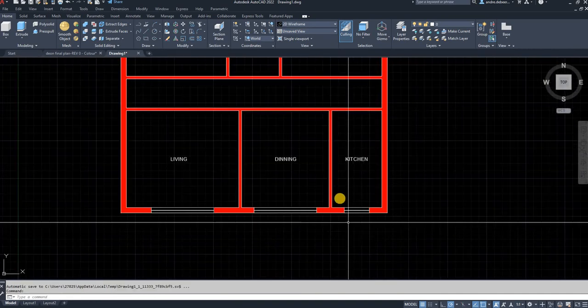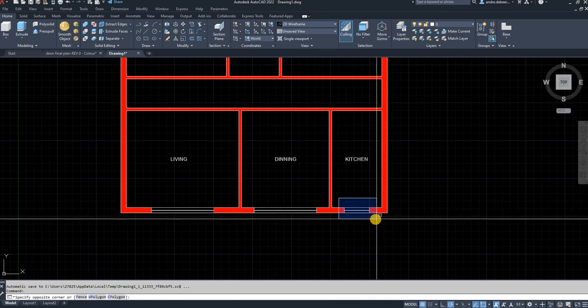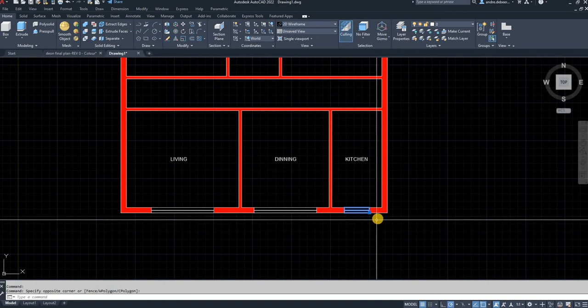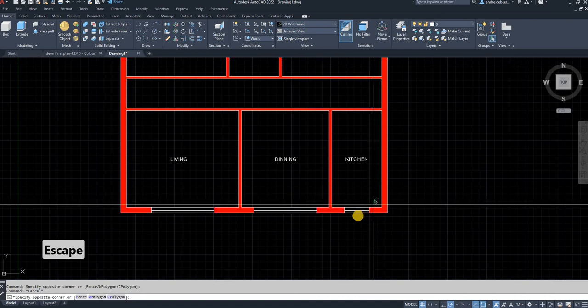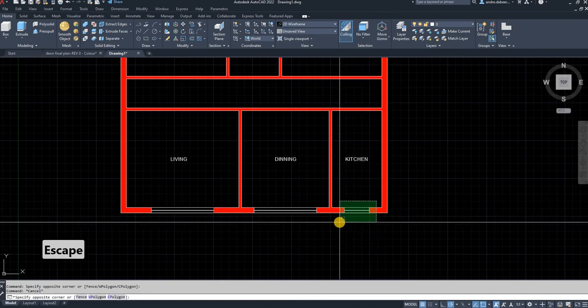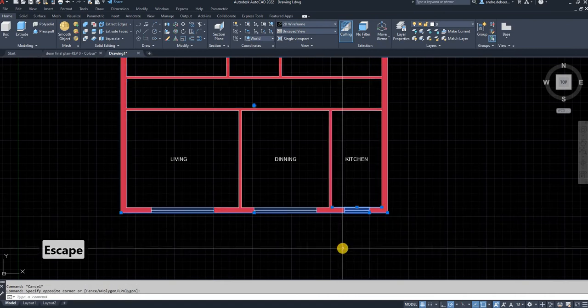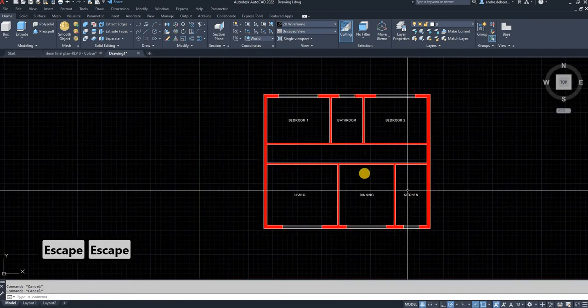So I don't know if you've noticed, but I select something with a blue block. Everything that's inside the block that doesn't cut the sides of the block is selected, and nothing else. But if I select from the other side with the green block, everything it touches, it selects. So that's just the difference between the two ways of selecting.